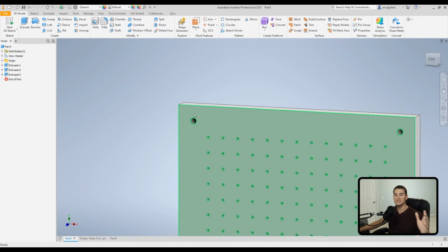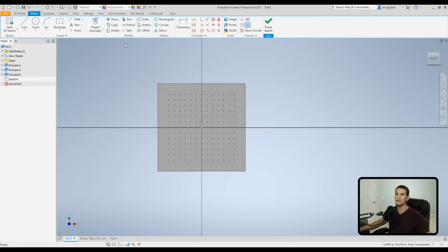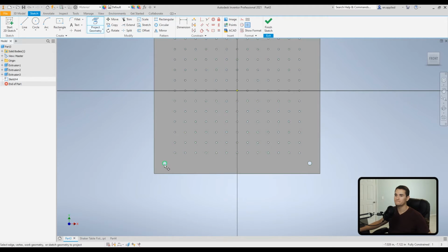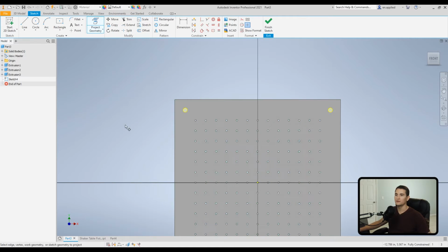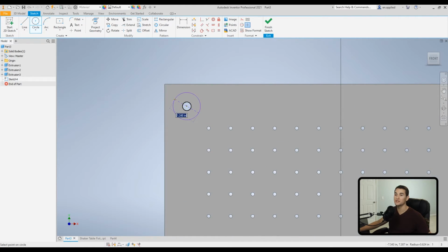So I'm just going to create a sketch on this plane with the diameter for these holes. So we'll go ahead and I'm going to actually project the geometry because I want these centered here. Okay. And actually these 3 were unnecessary. We'll just use this one here now that I think about it because we'll just use that circular pattern. And then this will need to be 0.688. So this just has some extra tolerance built in just in case the hole locations are a little off, and maybe our machine shop's not holding super tight tolerances. That's something else you want to think about. So we'll just click OK there.